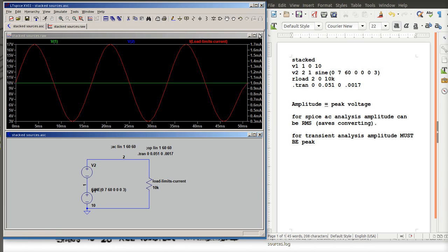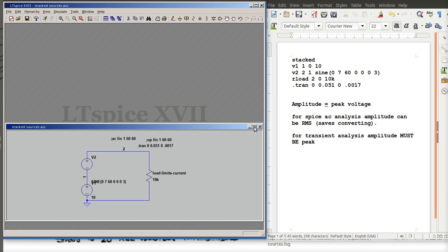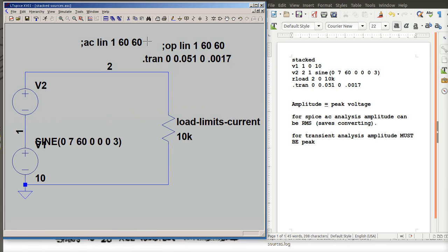We will use .op for most of the DC circuits. When we get into some AC circuits and we're only on AC, we'll probably do the AC analysis at a certain frequency. If we get a mixed signal like a superposition problem, then we either have to do multiple AC analyses, track answers, and add them, or you could look at it all in one as a transient analysis. But either way works. And if you can duplicate this, you will be in good shape.